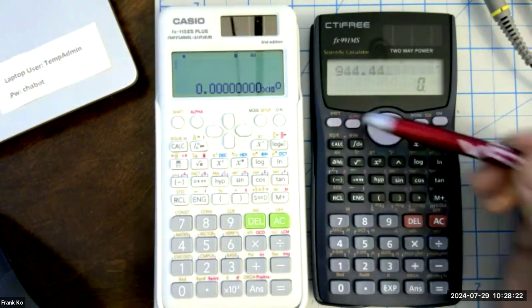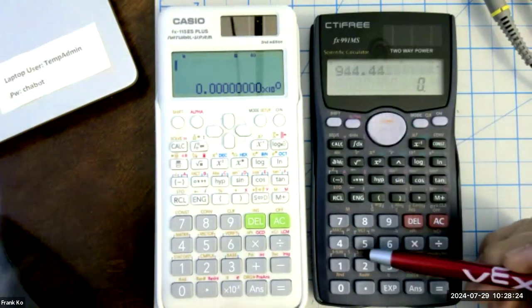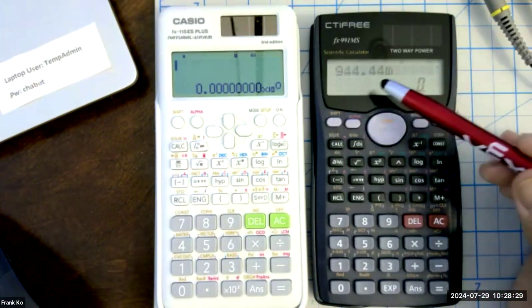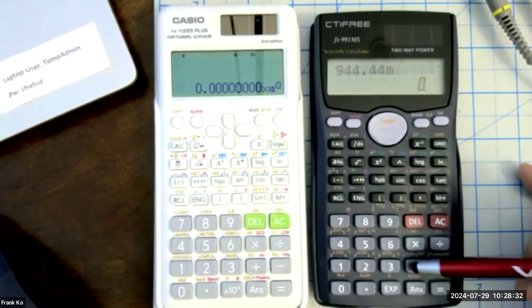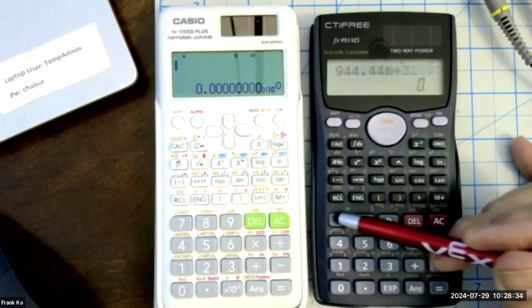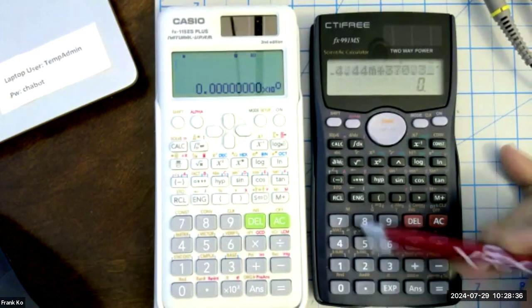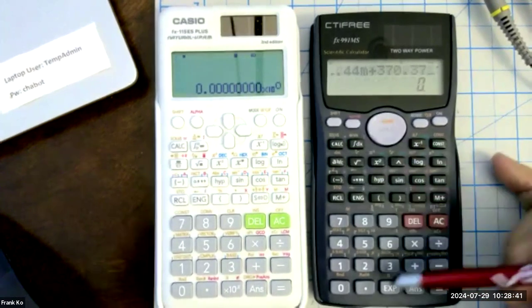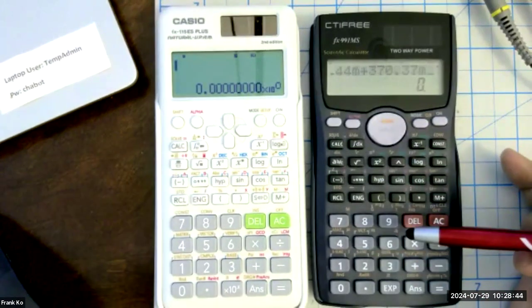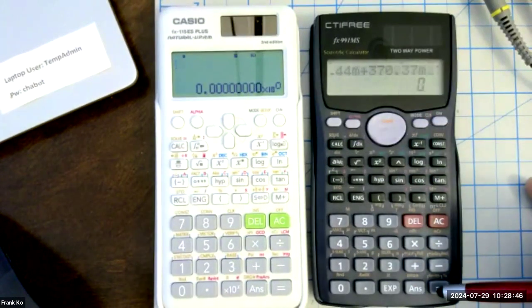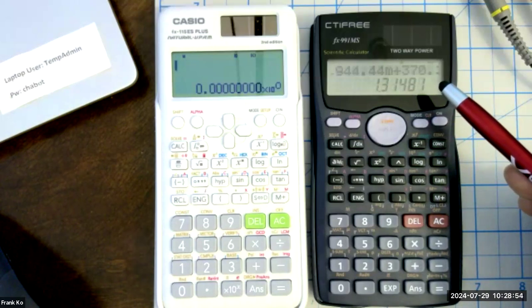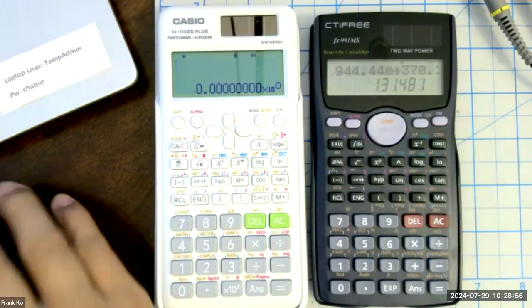944.44, and milli is engaged here as a shift milli. So you can now see I've got 944.44 milli, and now I'm going to add that plus the 370.37. And again, this will be a milli right there. And then hit add or equals. And there's my 1.31 VRMS. Okay,